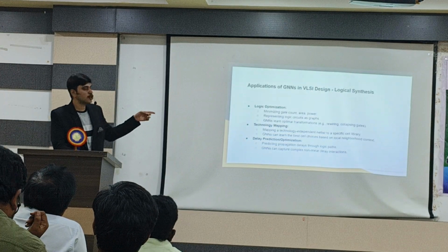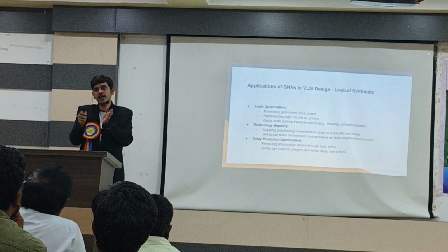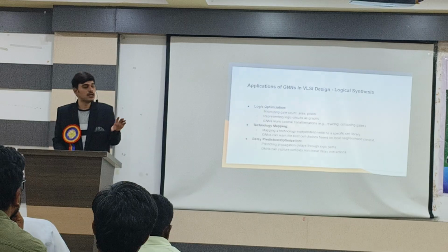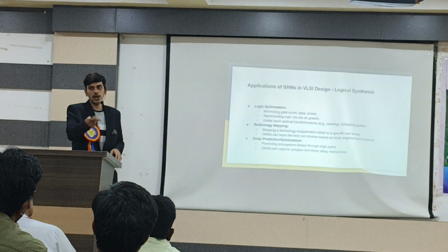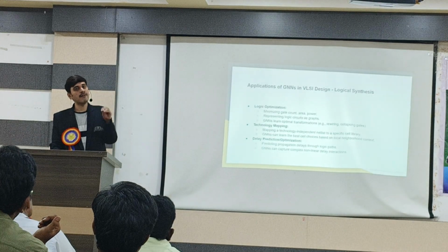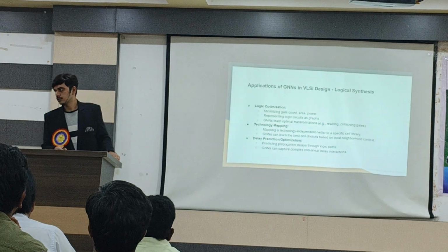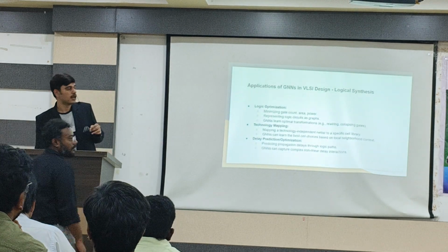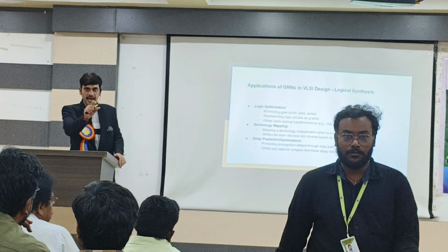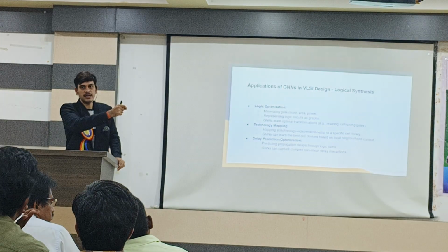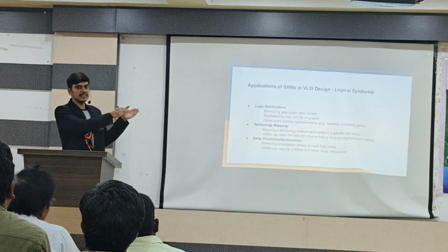So this logical optimization is like technology mapping. Because we have 4 nanometer, 3 nanometer, 2 nanometer, every technology node has different cells. They have different shapes, so the technology is different. Initially, a normal AND gate is one gate, but the AND and OR gates have different flavors, or different technology. Different technology mapping is there, right? So the technology mapping is done to a particular cell, the AND gate, which has 4 nanometer, 5 nanometer versions, like a 2 input NAND gate, 4 input NAND gate, 8 input NAND gate. Based on that, this gets set.